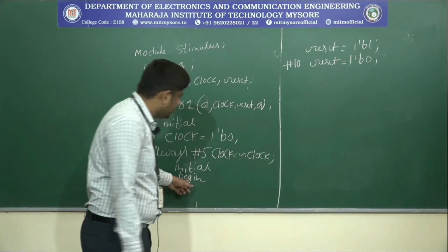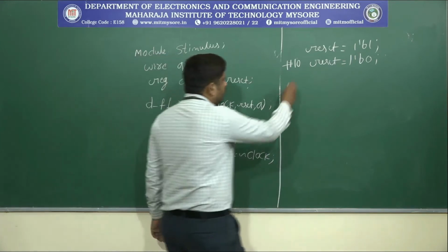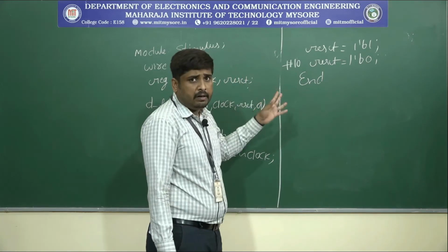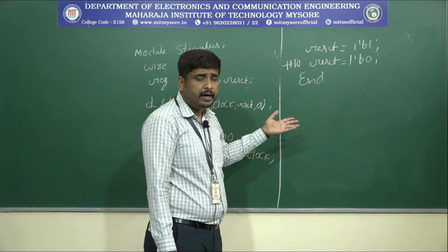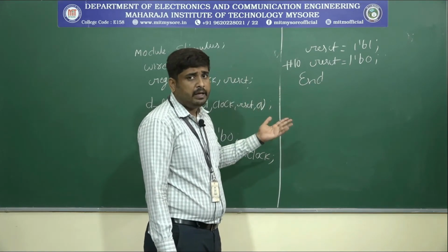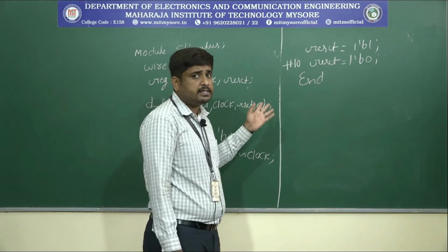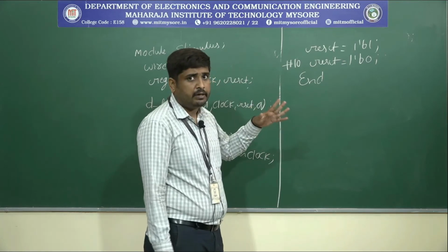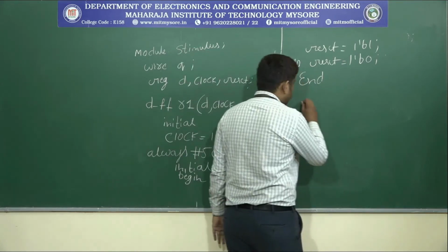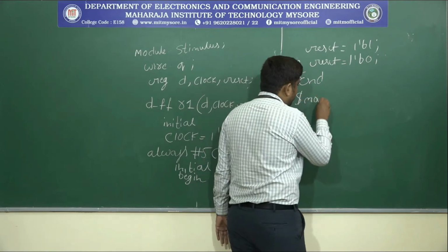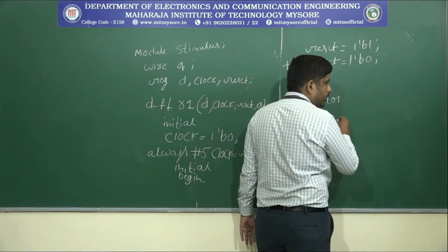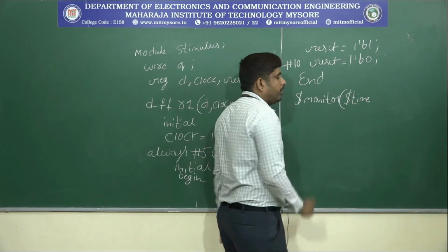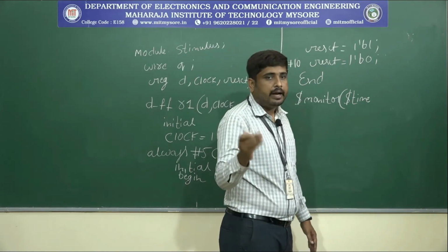Then after this, begin is a predefined word, and it should end with end. Up to this one we have to apply the data. Next we go to monitoring the data, as well as displaying the data. We already discussed in previous classes the monitoring operation and displaying operation. Here we concentrate on the monitoring operation, that is always start with $monitor. Inside the monitor you have to mention time, so that indicates $time, which we already discussed, that indicates the current simulation time.